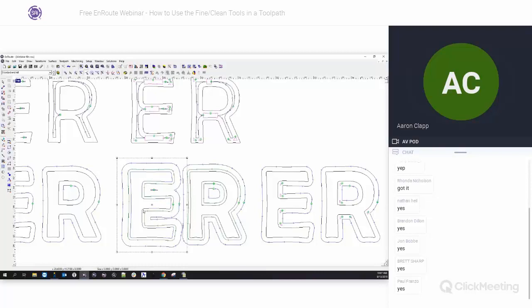Now our green tool path is not going to move really in this case because it's still cutting out what it can. So depending on what kind of materials you're cutting, you may want to make that a super thin pass, or you may want to make that really, really wide, depending on whether you're cutting acrylic or wood or certain things. If you're just looking to cut that last little bit off and just make that edge smooth, typically you're going to make that a pretty small setting.